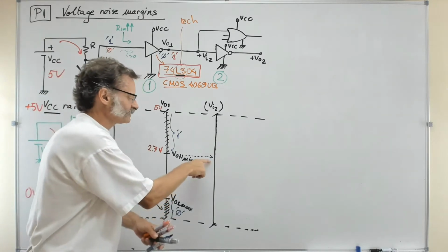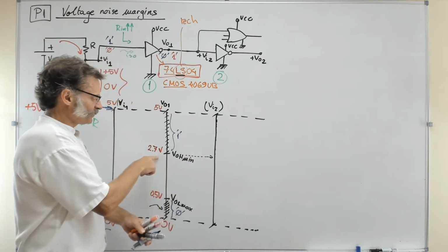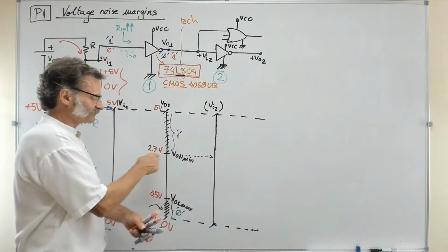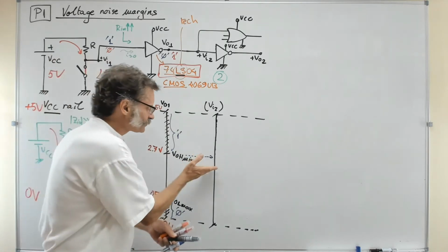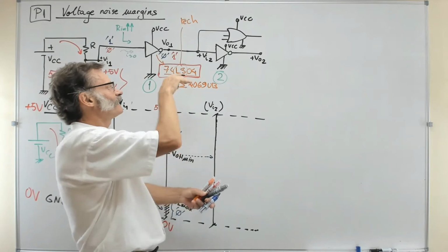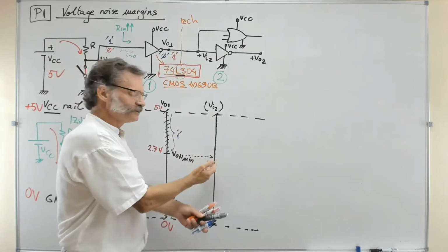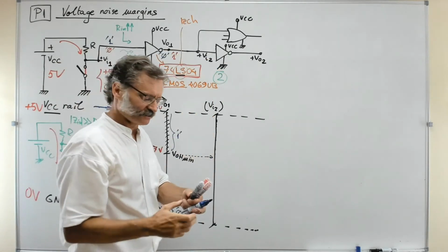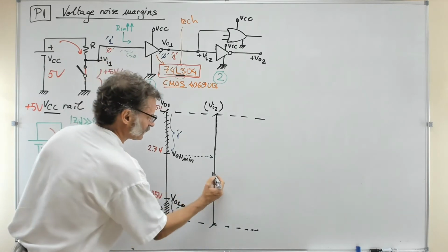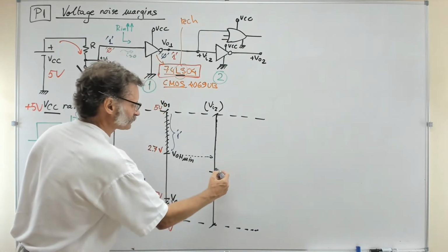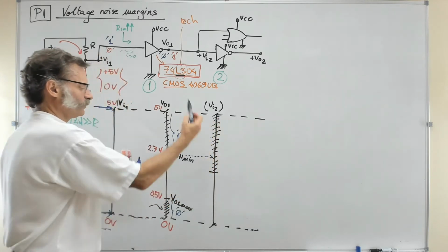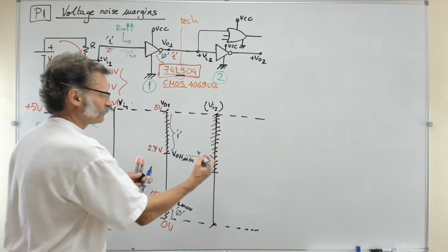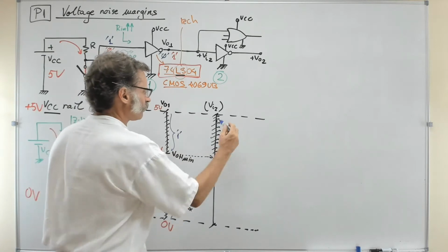Imagine that this voltage, which is very possible because it's in the data sheet as classified as the minimum voltage high, goes as an input to a value that does not correspond to a 1. You see, it has no meaning. So in reality, you have to take this like that. All this large voltage margin has to be what is called now a 1.